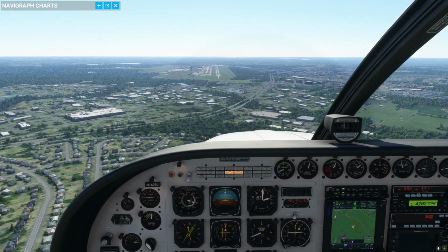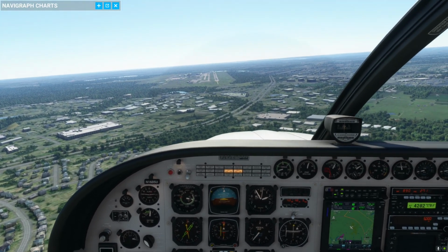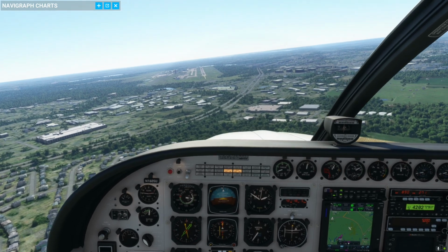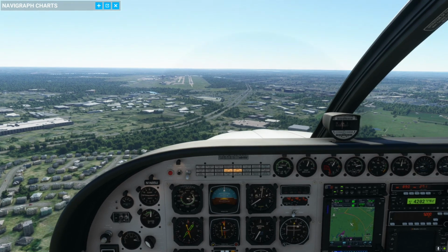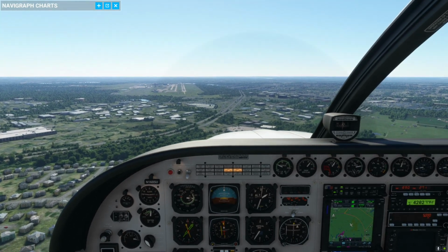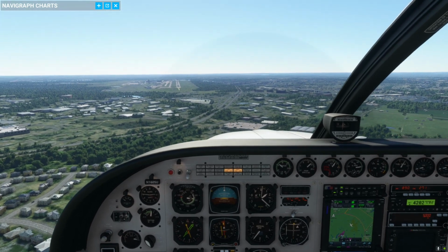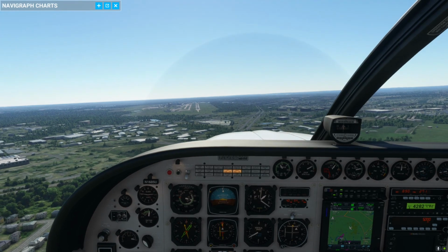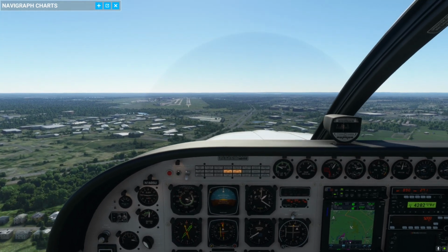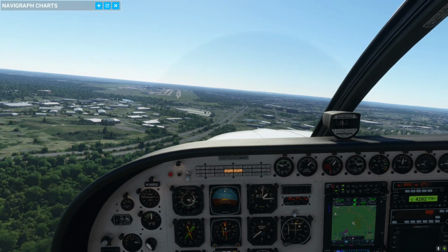If I had to guess, I can't see the lights. It feels like we're on course. I could tune the 2-3 right ILS, but I have to go look at it, and I'm kind of busy. Got hands going everywhere right now. I can barely see the PAPI lights, and I'm on. It says I'm on glide slope. So we want to keep our VSI at 500, since we're at full flaps.